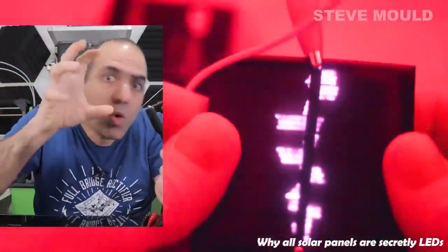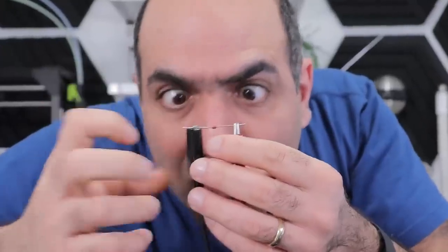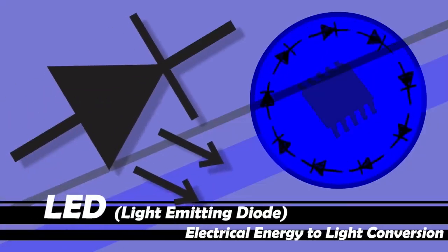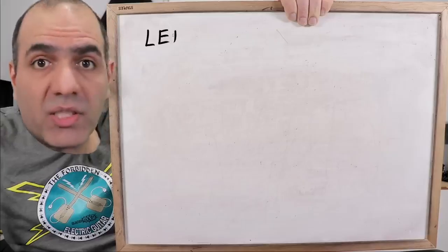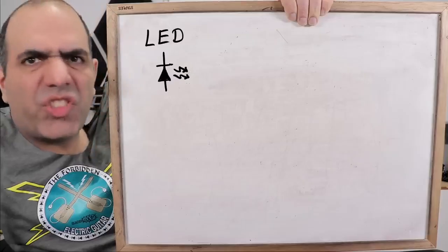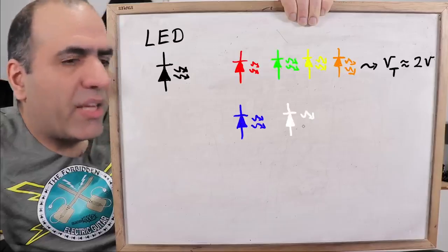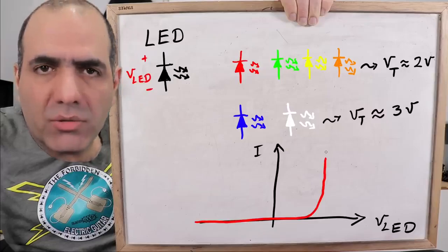But like Steve Mould mentioned in his video, if instead of pulling energy from them, we apply a voltage across them, they create light in infrared. Now we mess with the chemistry again and make them produce visible light. And we have LEDs! Efficient lighting, here we come! The only difference between LEDs and regular diodes is, well, beside the fact that they generate visible light, that their forward voltage drop is larger depending on their color. Otherwise, they could also be used as a poor man's regular diode.